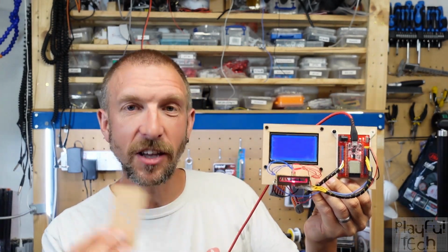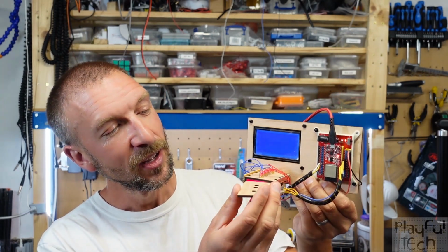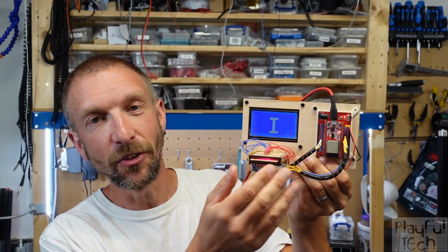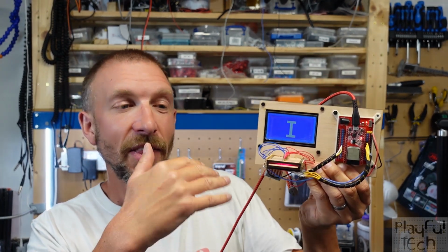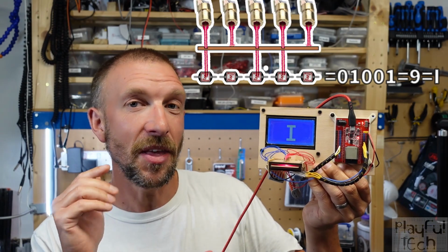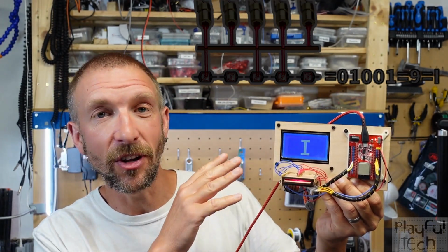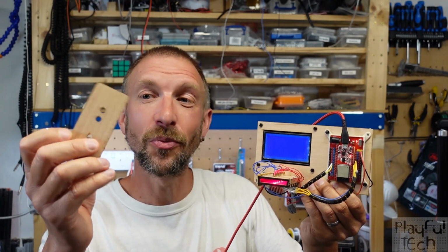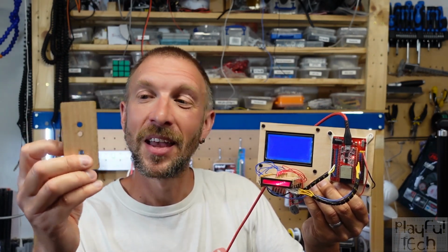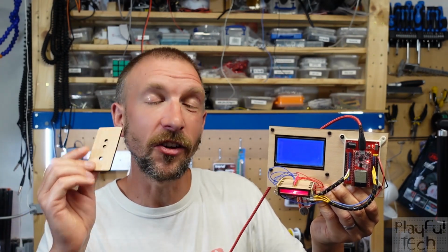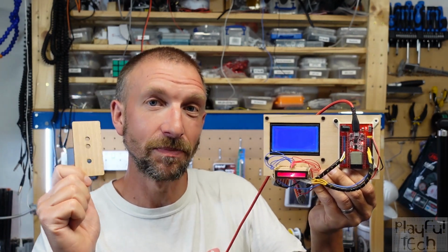So what happens if I pick a card and I push it into the slot? It's going to obscure a particular pattern of lasers from hitting the light dependent resistors underneath them. That can be detected by the ESP32 and interpreted as a binary value, and then that can be mapped to a letter, for example, or it could be used to uniquely identify an object. The cards themselves are very simple wood with some 6mm holes drilled into them, and if you have 5 lasers, as I do here, you've got the possibility to encode 32 different values.